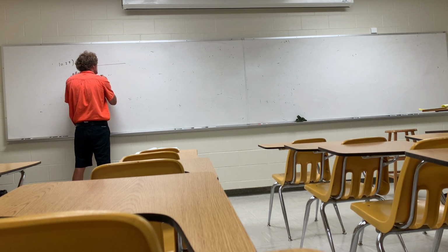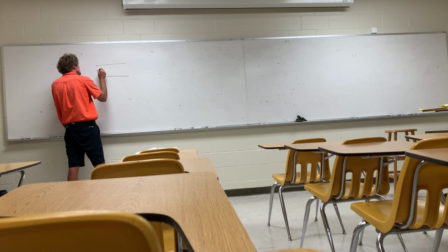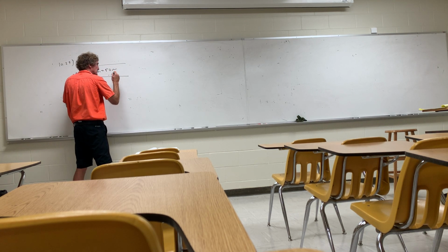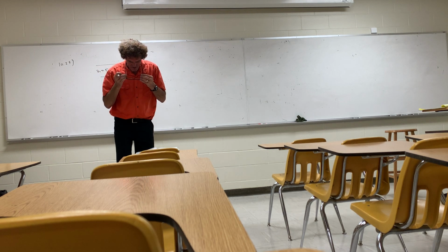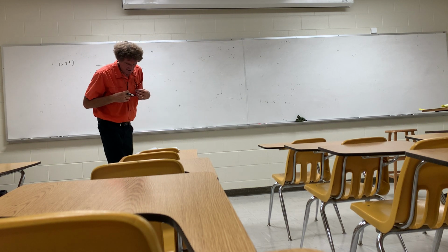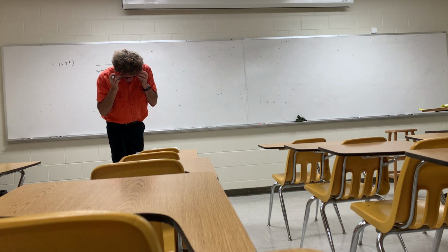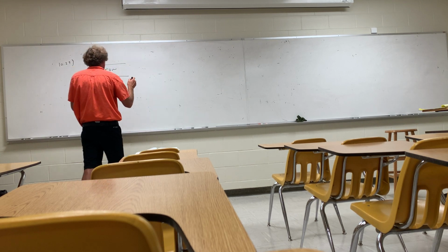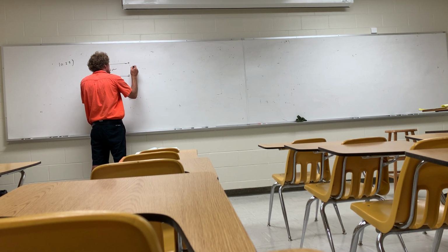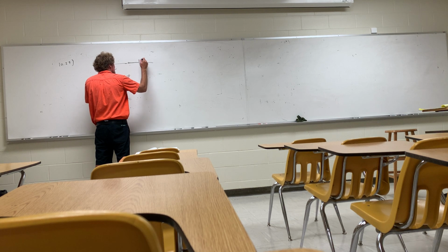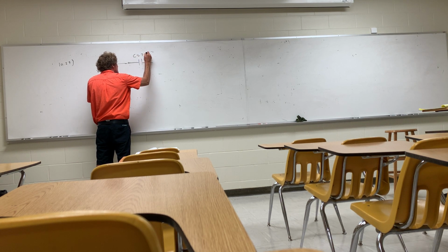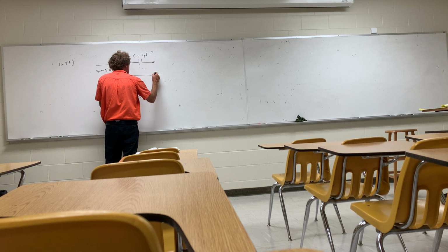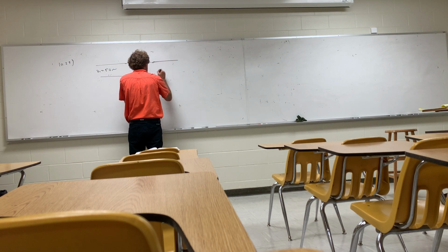So I have a transmission line here, Z naught equal to 50 ohms. I think he said 50. Yeah. And then he has a 2 picofarad capacitor. So he's just going to cut the line and put a 2 picofarad capacitor in series with that, and it's going to be connected back to a 50 ohm line.